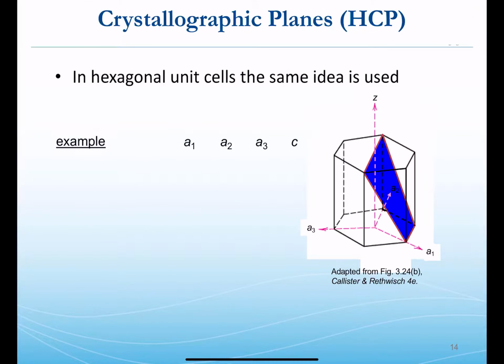Okay, now we haven't addressed hexagonally close packed systems. Here the ideas are very similar in that we need a fourth bit of information. So here we're kind of pushing ourselves outside of our comfort zone in that we have to move out and away from our Cartesian coordinate system and now use a 4-axis system to represent space.